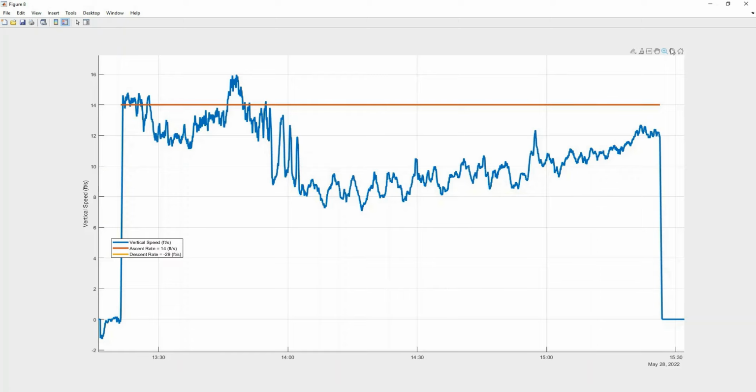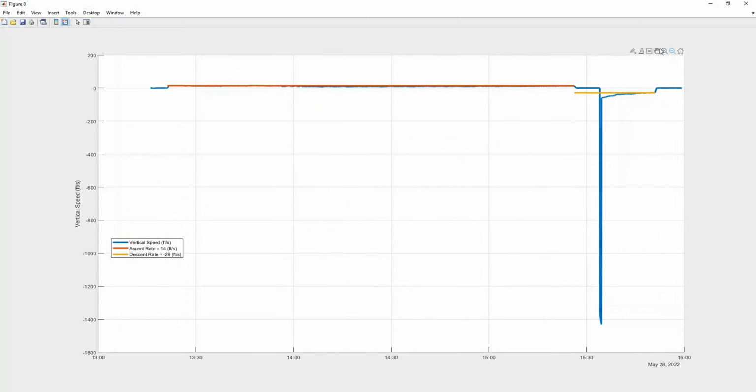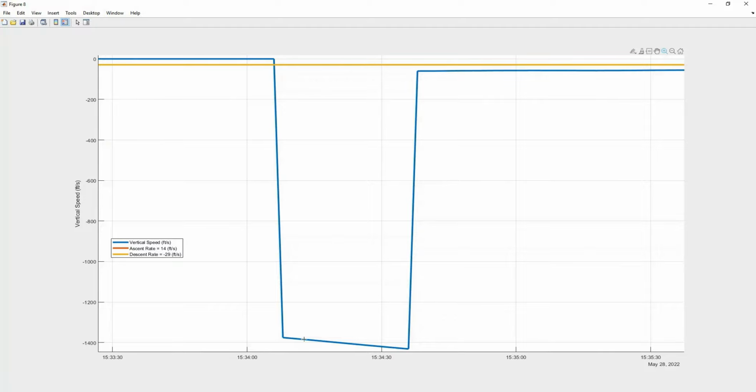Now again, this is what's fascinating about the burst. Look at this. Gee whiz. When it burst right here at 3:26, look at our descent rate. Look at this. Woo, man. Again, I don't think you can trust this because this is probably from GPS, and we saw that we lost GPS lock, but yeah, that's ridiculous. 1,400 feet per second. No, that's probably not reasonable.